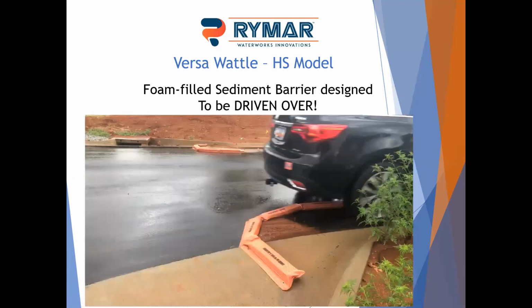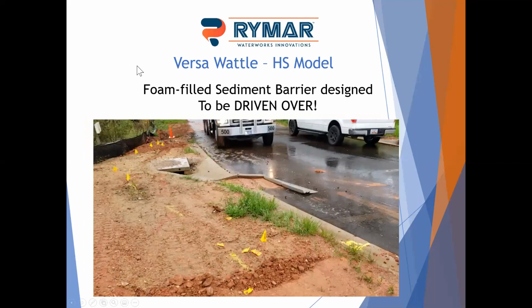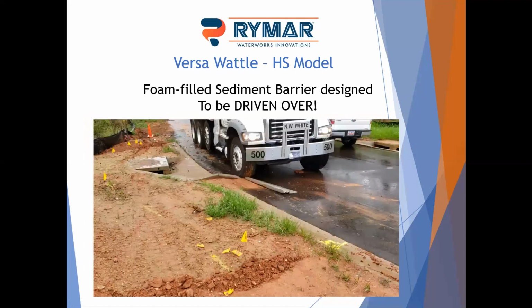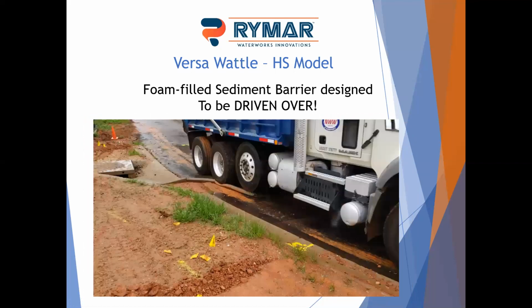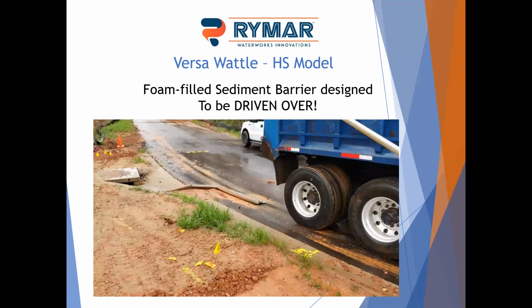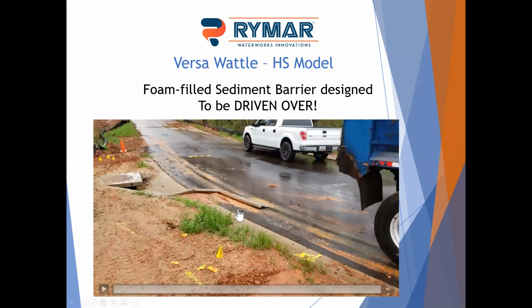So we tested these for 9 months or longer, and whether it's driven over by regular vehicular traffic or even a dump truck, they do hold up and they last for the life of the project, at least a year. We've had some in the field longer than that. They do need to be maintained. It takes just a simple spade to scoop out sediment. We've had a contractor or two try to clean it out with a skid steer, and they're not designed to handle that, so they're not going to hold up.